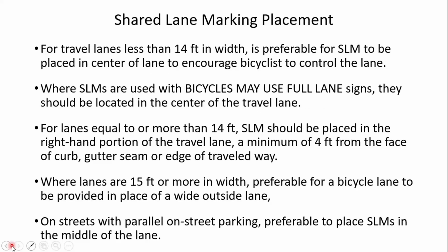And here's some guidance with respect to placement of the shared lane markings. For travel lanes less than 14 feet in width, it's preferable for the shared lane marking to be placed in the center of the lane to encourage bicyclists to control the lane. Where the shared lane markings are used with bikes may use the full lane signs, they should be located in the center of the travel lane.